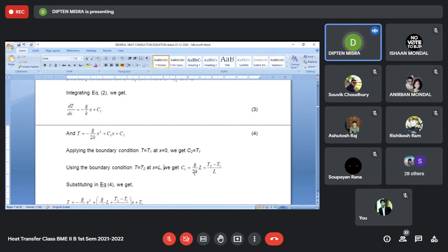So your heat flux becomes a simple constant that does not change along y and z on the left hand side of the wall. So the heat flux is uniform over the entire surface of the wall, that left hand surface. So to find out the heat transfer rate, we don't even require to integrate. The heat transfer rate will be simply that heat flux, which is uniform throughout the wall, multiplied by the surface area of the wall, that is given by H into W.